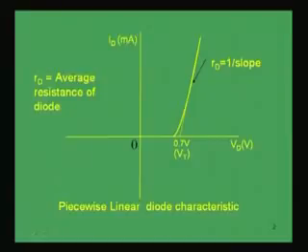Due to the barrier potential, current is 0, and as soon as the voltage applied across the diode is greater than 0.7 volt for silicon, we are taking an example of silicon, the current rises sharply. This is the characteristic curve, and in the reverse bias of course this is almost 0, so it will be coinciding with the 0 line.